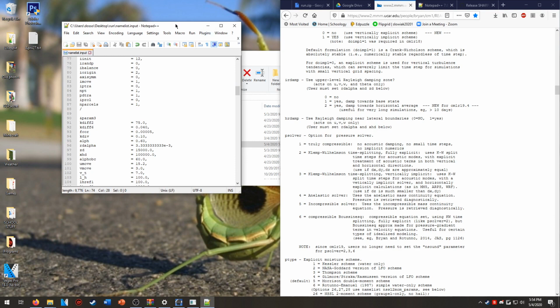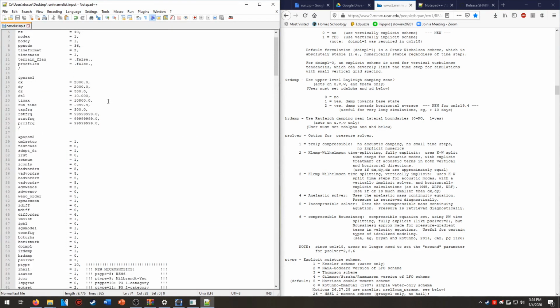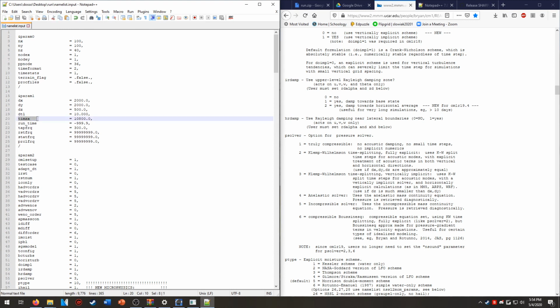Now there's a couple of other things that are easily understood on here. This right here, timax, this will be how long your simulation will generate out to. So it'll generate out to this amount of time. I don't really recommend simming it all the way to the end, because not all the time you'll have a cell that's still in the domain. It'll move out of the domain or die or become a line or whatever. This is how many time steps go into it. So if you're counting down, this is each time step. So it'll go from 10,800 to 10,500. Really simple.